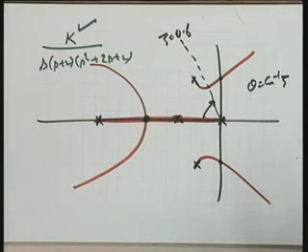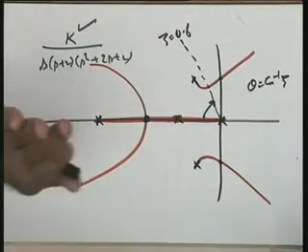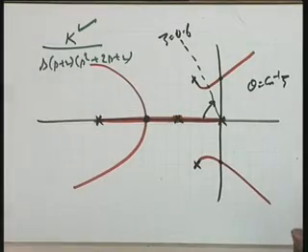Now, my design problem starts, please. It's a simple design problem, only gain adjustment. The PI, PD, other controllers I have not taken. Only the amplifier gain can be manipulated. And my design question to you is this: give me a suitable gain K, adjusted using the amplifier, so that the closed loop system has a damping of 0.6. So, the starting point is that I draw a damping line. See the procedure, please. This damping line intersects this particular root locus at this point.